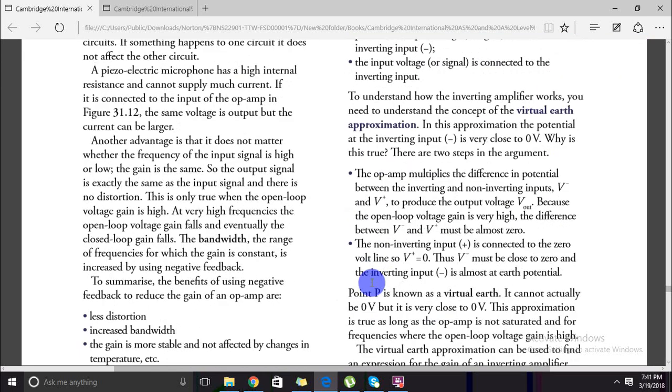So if they ask you why do we have this, why do you want to have a G naught of 1, it's not going to do any amplification. In a comparator circuit, there was amplification observed, but it wasn't exactly what we were looking for, were we? That was just a byproduct of it. And the byproduct was what was allowing us to use it the way we wanted to. So what does it do? Acts as a buffer between electronic circuits.